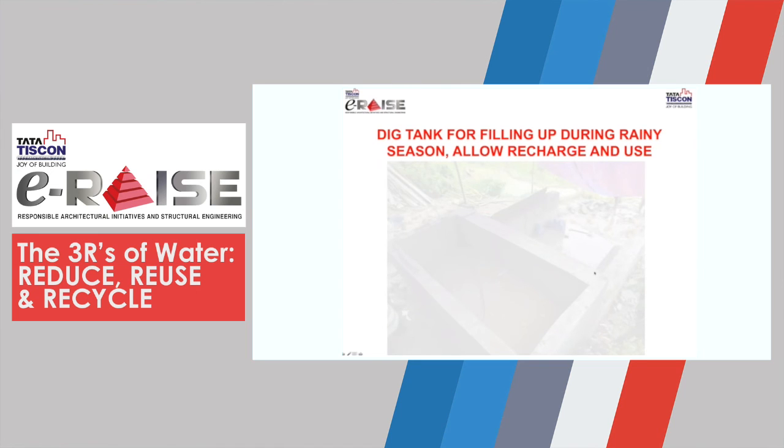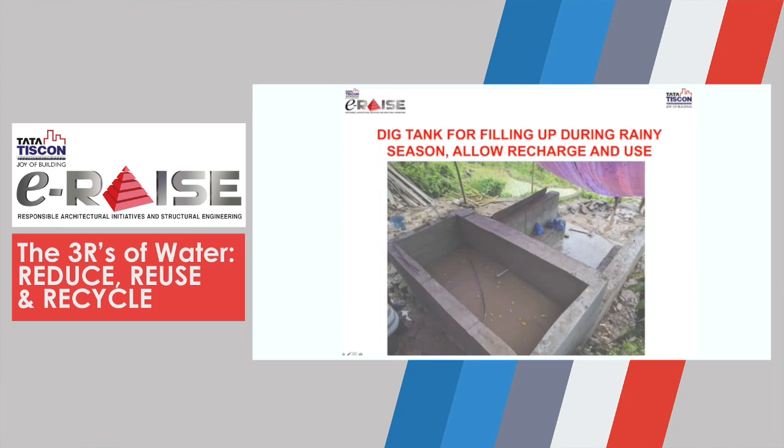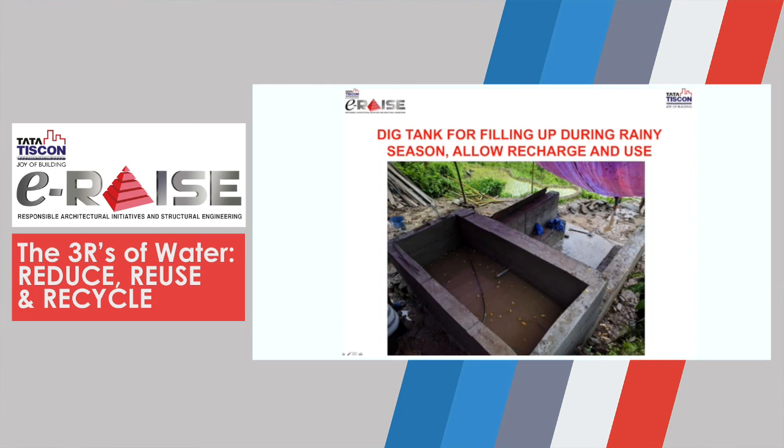Right. Now, dig tank for filling up during rainy season. This is also something that has had a lot of publicity, which is that you dig a tank, the hapas as we call them locally, and allow the rainwater to collect. And then what happens if you allow the rainwater to collect? Then recharge, the most wonderful thing. So the base should be made of materials which will allow the recharge to happen. And if you allow water to stand for a while, whatever little impurities there may be will settle down, and you can easily then use the water that is on top. So digging the tanks or the hapas can be of great use.